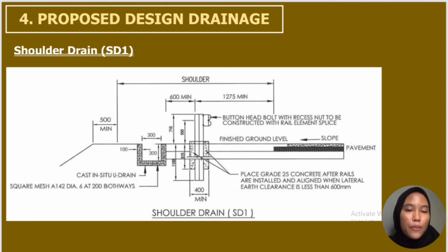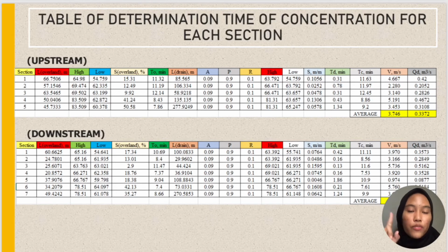The fourth step of the process of designing road drainage in the area of Kampung Sungai Yap is design calculation. It is a calculation process to determine the flow rate of the design. So the first step of the calculation is to determine the overland sheet flow path length, LO, for the flow path in every subcatchment to calculate the time of concentration of each subcatchment. It can be determined by referring to the subcatchments that have been made using AutoCAD.